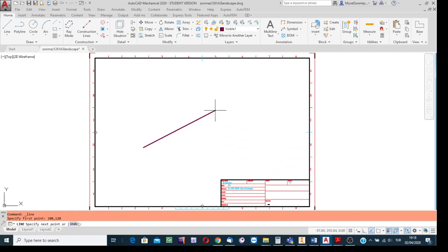But it is tricky, you know. If the dynamic input button is on, then always write the angle as positive. If the simulated arc is in this sense, then as measured in the counterclockwise direction, write the number positive.